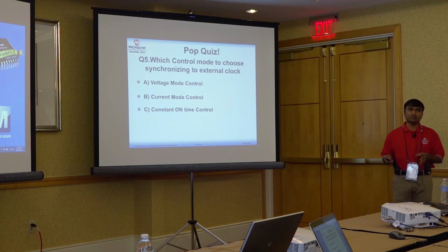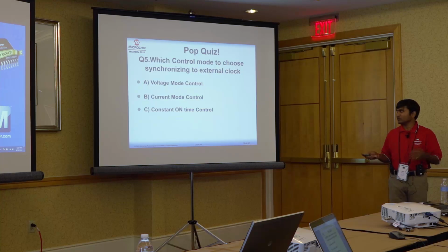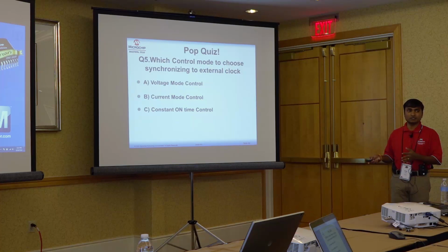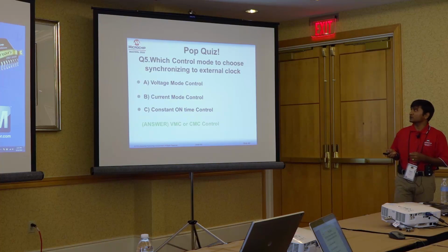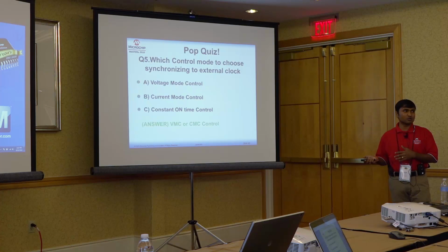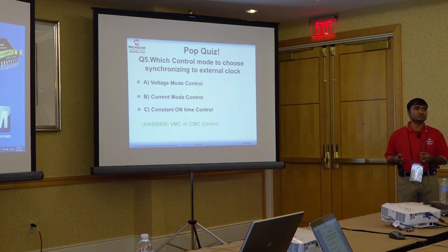That problem has not been solved yet, but if you are okay with some little frequency deviations, I think the COT controller is best. But for synchronizing to an external clock, voltage mode control or current mode control is generally chosen.